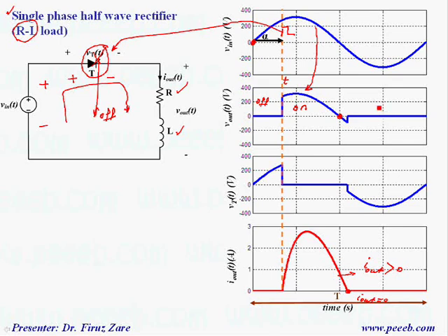So here the thyristor is off. We can see that the output voltage corresponds to this area plus that area. So the output voltage depends on load impedance, and we need to find this turn off time to be able to find the output voltage.